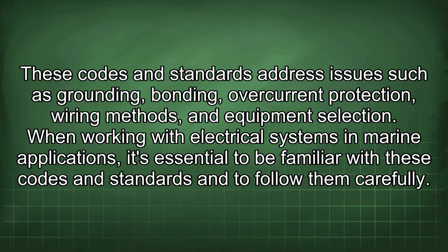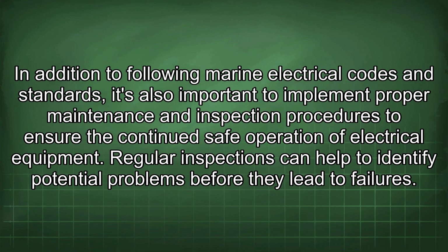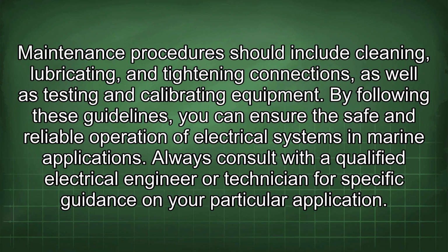When working with electrical systems in marine applications, it's essential to be familiar with these codes and standards and to follow them carefully. In addition to following marine electrical codes and standards, it's also important to implement proper maintenance and inspection procedures to ensure the continued safe operation of electrical equipment. Regular inspections can help to identify potential problems before they lead to failures. Maintenance procedures should include cleaning, lubricating, and tightening connections, as well as testing and calibrating equipment.